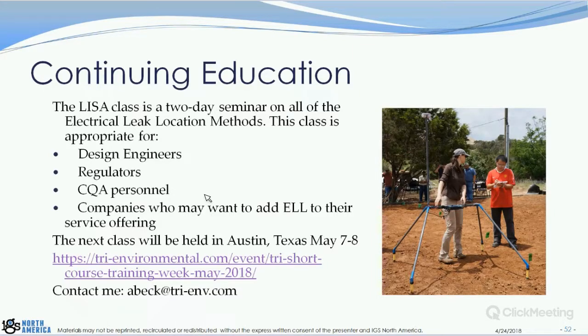But once the site gets smaller and smaller, it costs more per acre. You have a mobilization cost and you have a daily testing cost. So a 1 acre facility might cost the same as a 4 acre facility because it's mostly mobilization and setup. But to give you an idea, it's $1,000 an acre, and if you have something greater than 10 acres, it should go down from there. For very large sites, like 100 acres or more, I imagine it could go down to $500 an acre.